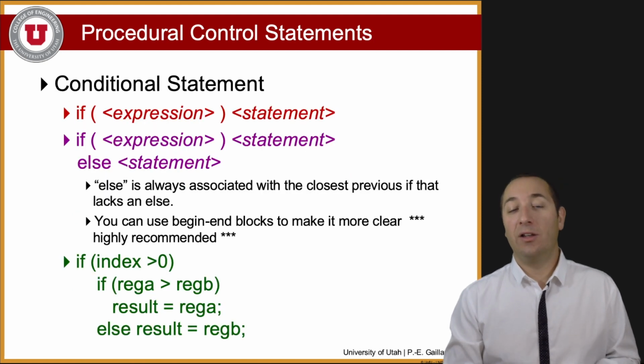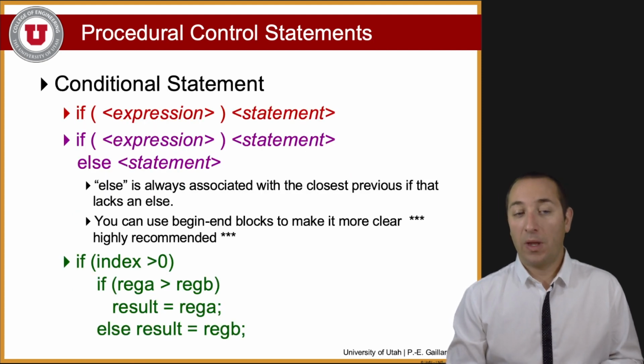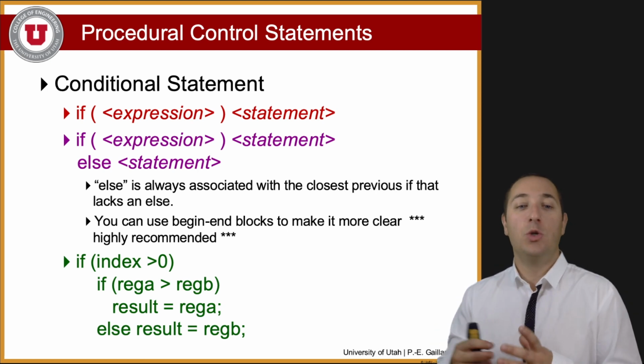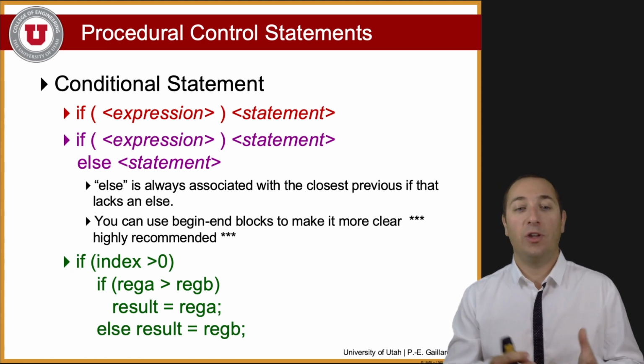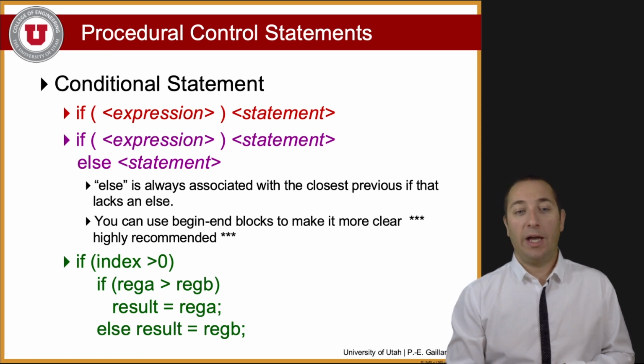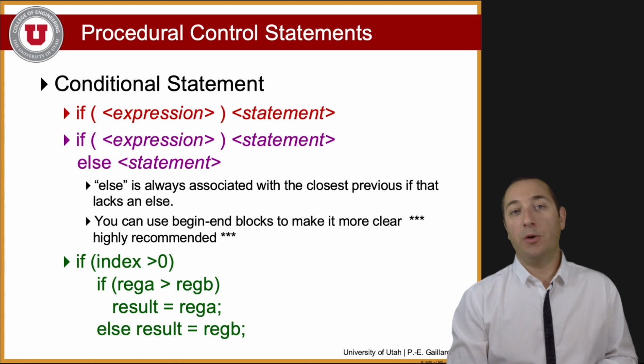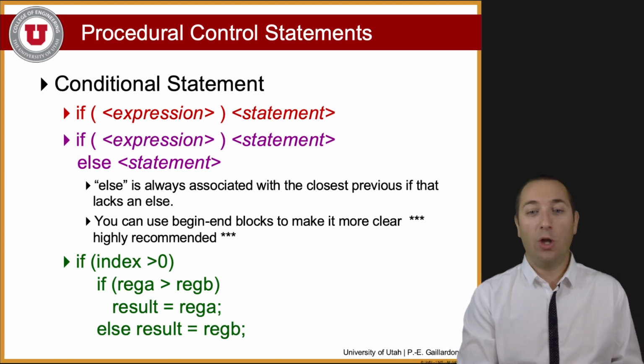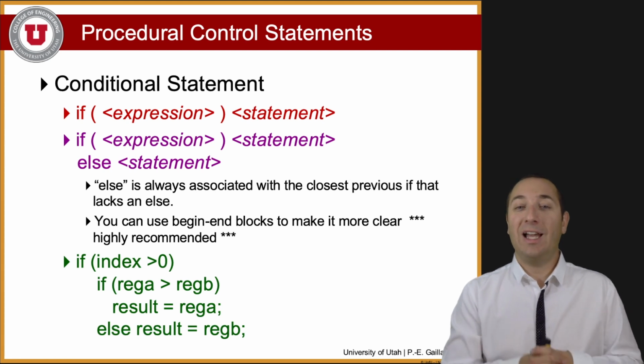While inside procedural statements, I can have conditional operations. You can use if statements with if expression, then do something, or if else operations. I'd like to point out that the else is always associated with the closest previous if that lacks an else.